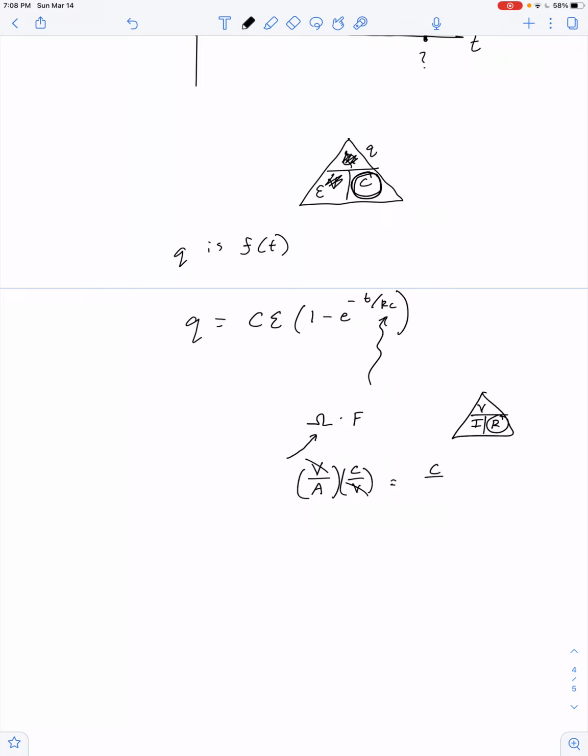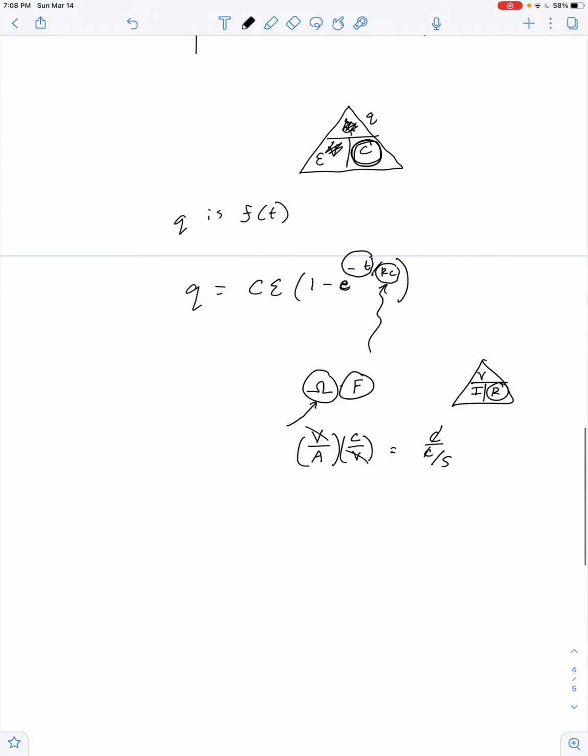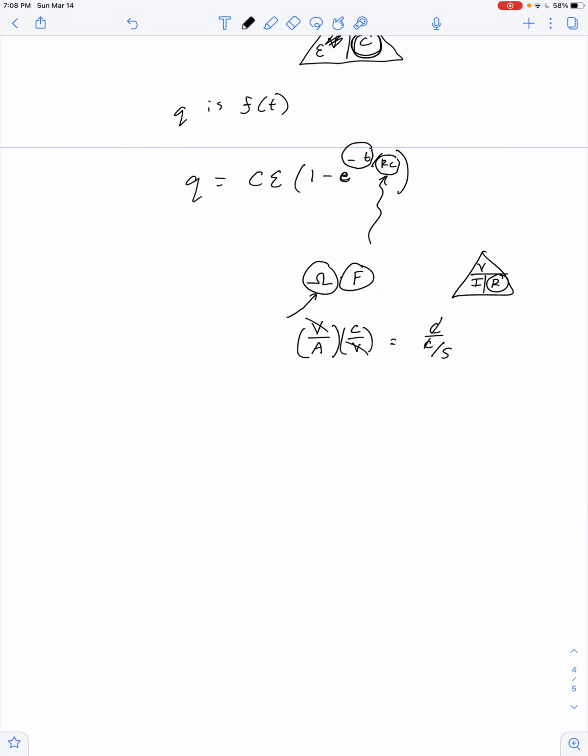Let's see, a coulomb per amp. I don't want to call it an amp. I want to call an amp a coulomb per second. Oh, yeah, so we end up with seconds. Ohms multiplied by farads is seconds. Well, it has to be, right? I can't raise the base of the natural logarithm to some numerical quantity that has units. I can only raise it to just a strict numerical value. So if the numerator is time, then the denominator has to have time units. So what time value is the product of R and C?